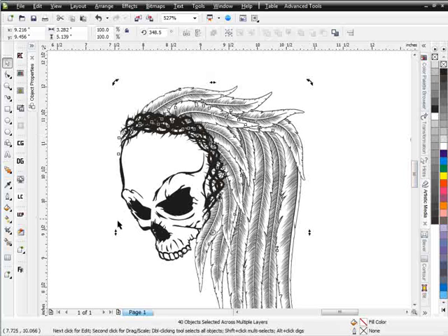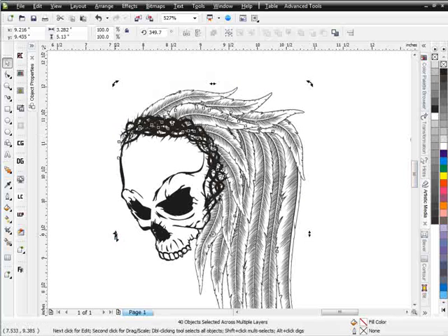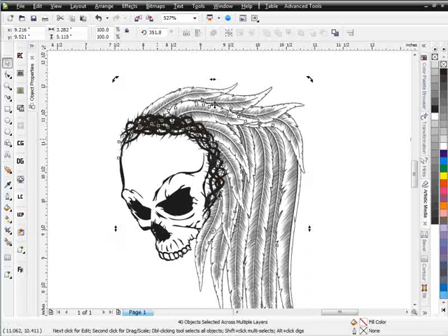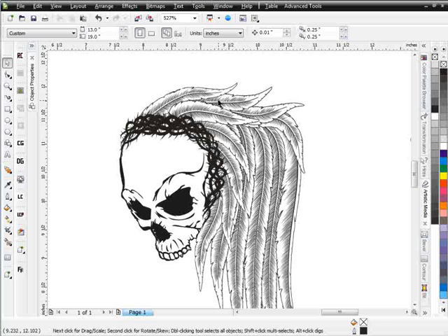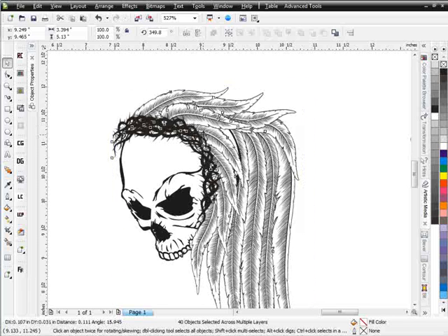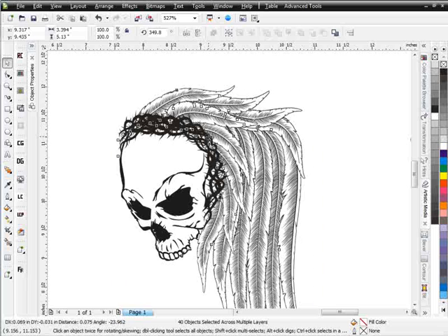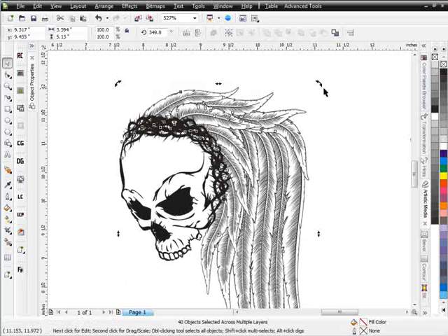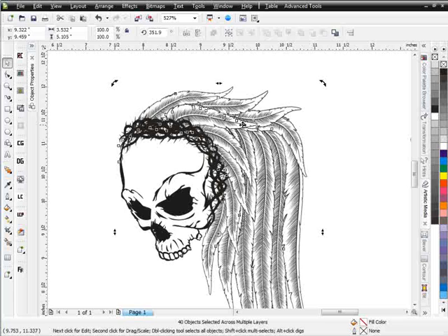Click that off here, and then just see if we pull this down here a little bit and arch this up a little bit, see what type of look we start getting. I'm going to hit Control Z, click on this again, and arch this way. Let that process, and then I can reposition onto my skull here so it's kind of balanced with the flow of the skull relating to everything that's going on with my brushes.